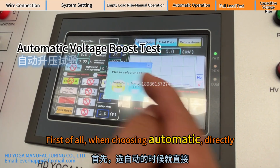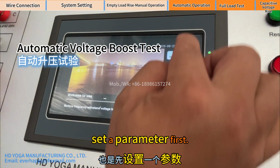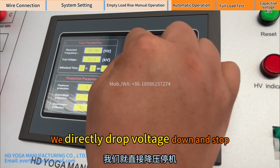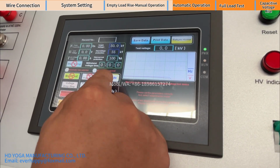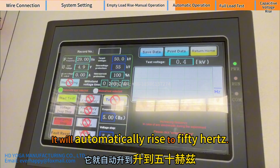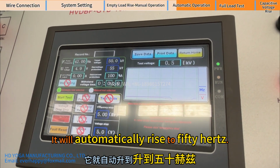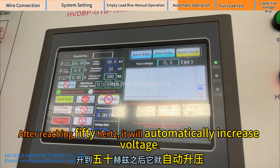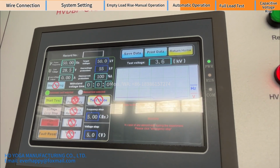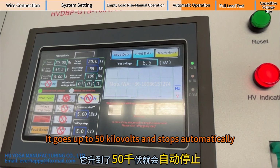First of all, when choosing automatic, set a parameter first. If it's 50 kilovolts at 50 Hz, we directly drop the voltage down and stop. Select the mode, automatic. Click Start Test. It will automatically rise to 50 Hz. After reaching 50 Hz, it will automatically increase voltage. I don't click anything. It goes up to 50 kilovolts and stops automatically.